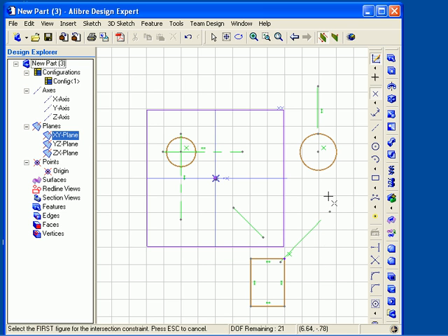For that, I'll click the corner of the rectangle, and it will snap to the theoretical intersection point of the two lines. Now you will see that if I change the location of one of the lines, thus moving the theoretical intersection, the corner node of the rectangle will move as well. This concludes this segment of the video.